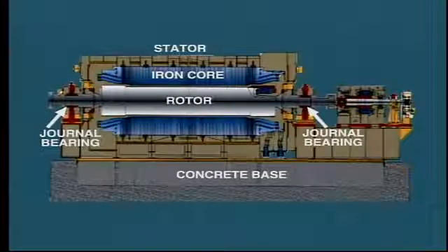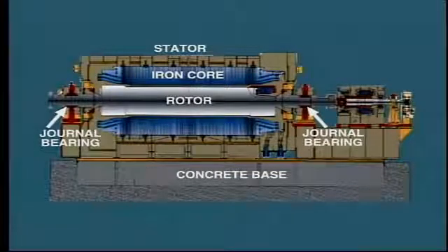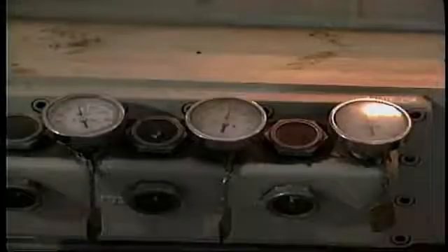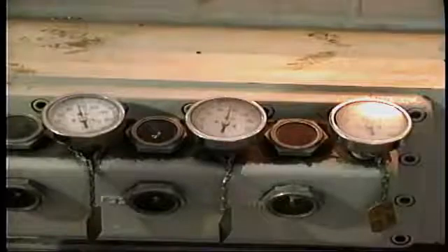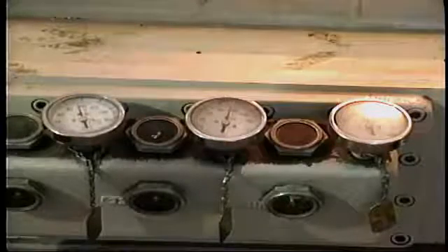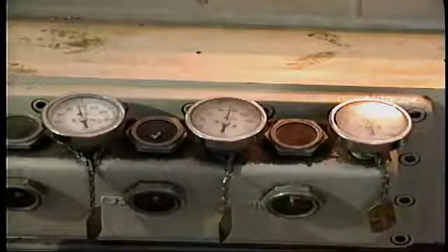A forced lubrication system is required for the bearings. Pressurized lube oil may be provided from the turbine lube oil system, or in some cases, a separate generator lube oil pumping system is installed.